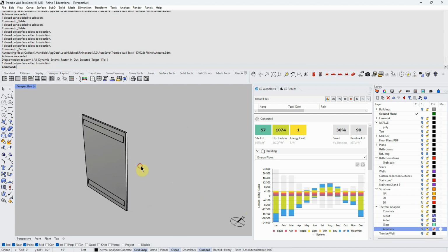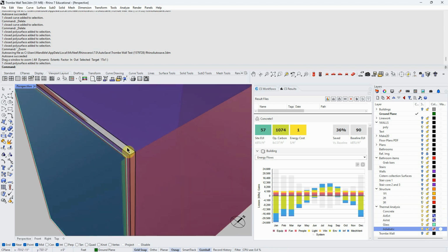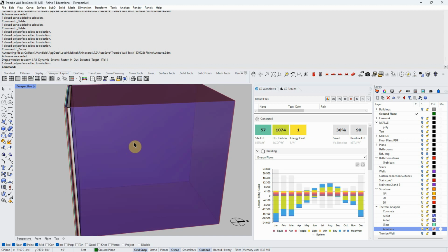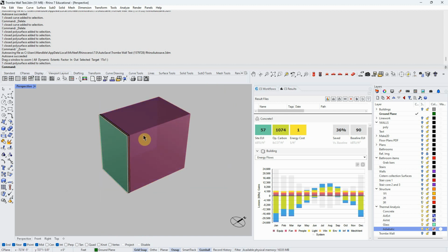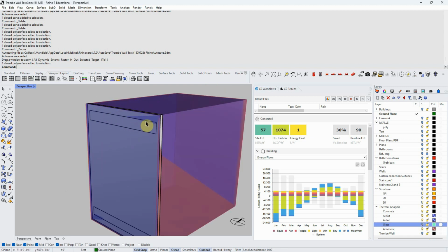a concrete wall that had air behind it and in front of it, and then a piece of glass in front of that, and then an adiabatic surface all around it. And so the idea would be that then I run a thermal simulation. This airspace would heat up behind this glass, and that heat would move through the concrete into the interior air volume. The problem that I ran into was that, so at first I just tried it without any cuts